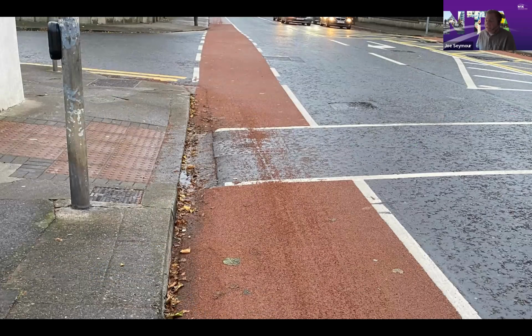Other things that we need to consider sweeping up along the way: when we add the epoxy resin colored material on a cycle lane, it does get swept straight away after the contractor has put it down. But it needs to be done a few times, because this material here was done in August, and it's still quite loose. And this is quite hazardous at junctions for cyclists, because they will skid on that material if you're not careful. So you do need to go back in a few times before all the material is removed.